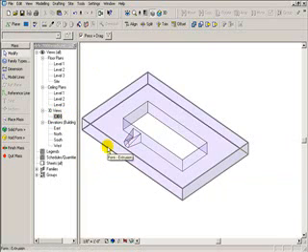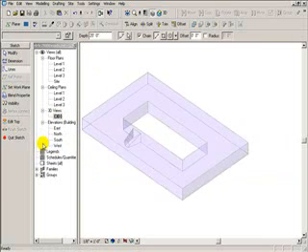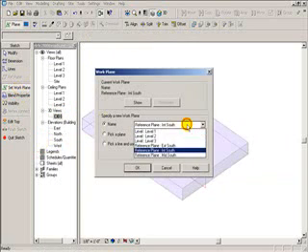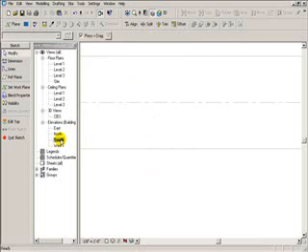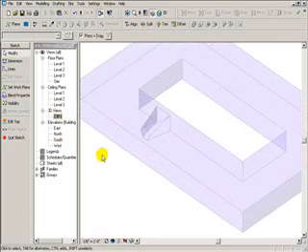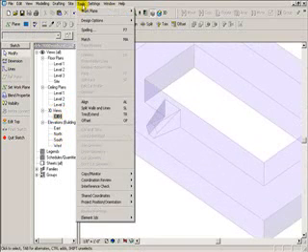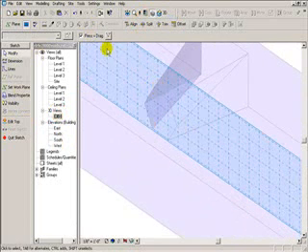So what I'll do again is start my void blend. And I'm going to set my work plane. And this time I want my work plane to be the mid south. And I'll tell it OK. And we'll go to my south view again. Actually, we want to do this in a 3D so we can see. And we're going to turn on our work plane again. And I want to keep my existing geometry that I have there.